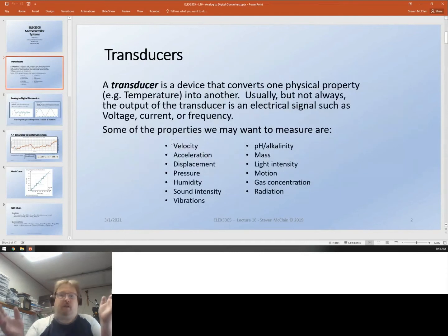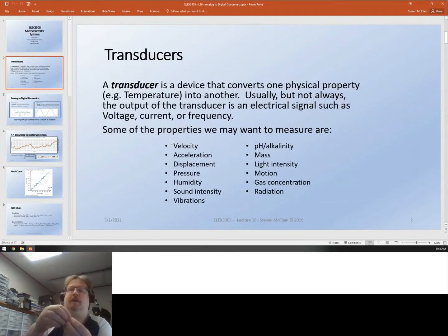This is the sensor itself, right? You want to measure temperature, right? So you can use a temperature-dependent resistor, or you could use a diode junction that changes characteristics over temperature and run current through it and measure the current. And you electrical guys, you should be seeing this stuff, right?